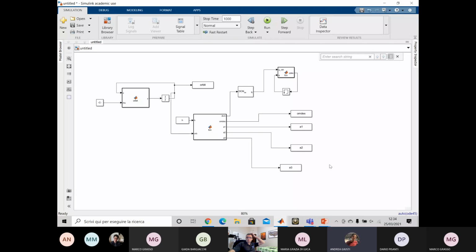Sorry. So what we're going to do now is the Q desired is the desired quaternion of the spacecraft in the inertial reference frame, and that's okay. So you don't need to modify that. But the omega desired, the way it's expressed now, is expressed in a basis that is in ECI, not the basis of the spacecraft. So you need to rotate that vector, project it into the spacecraft axis. And to do so, you need a DCM that goes from inertial to body. And to assemble that DCM, you need the quaternion, for example, of the spacecraft.